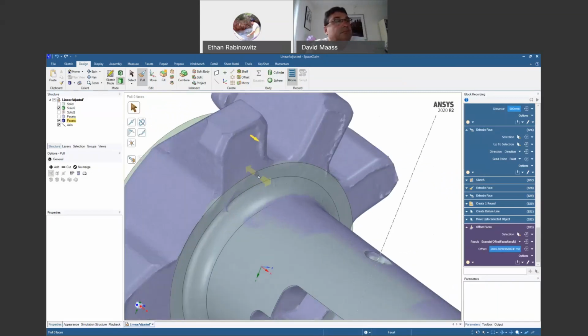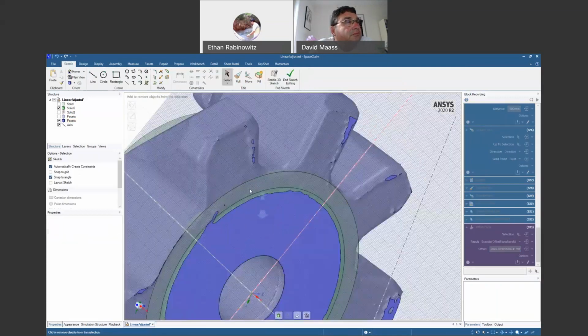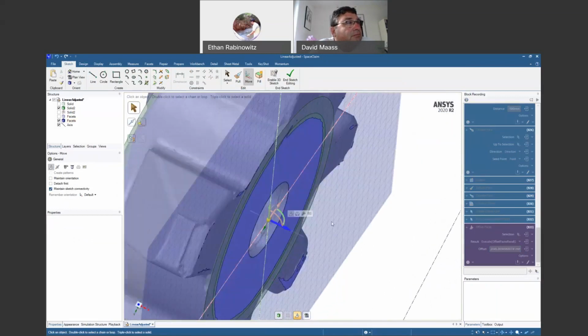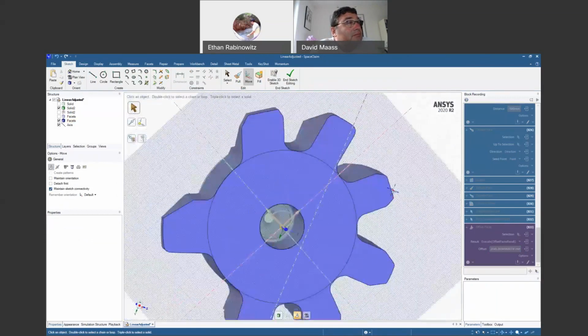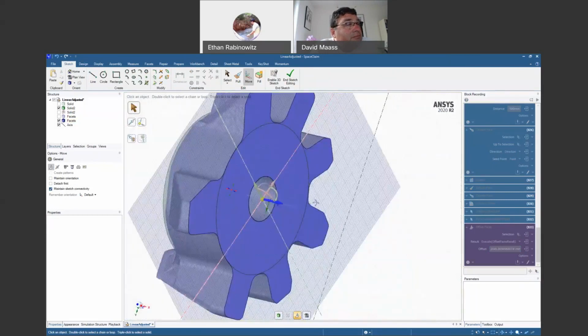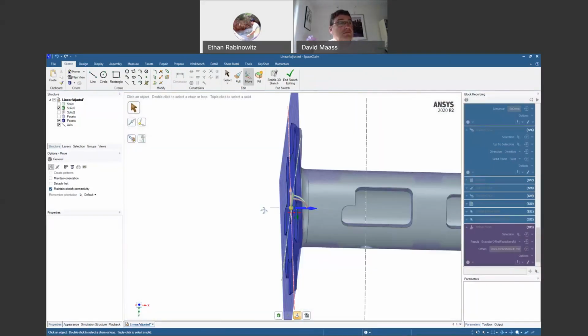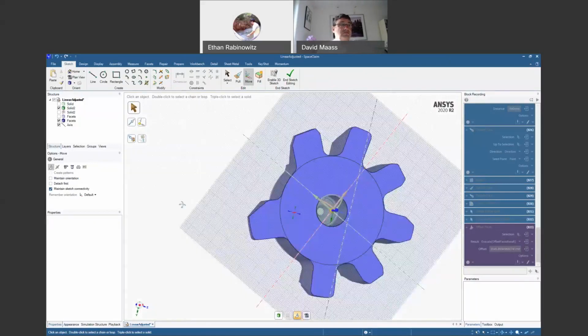All right, so what I'm going to do, this right here is a planar face, and I want to make sure that what we create is aligned to our body. So I'll select that as my starting point, go into sketch mode. Sketch mode down here isn't too useful because we're not making a good cut up there. So we'll use this move grid button, which puts the move handle on the grid, and we'll move it up to a nice clean cross section. I think that looks pretty good. So I just want to make sure I'm not missing anything if I look from the bottom. One nice thing about cross-section view is it auto hides part of the model, which we can change, but I think that's pretty useful.